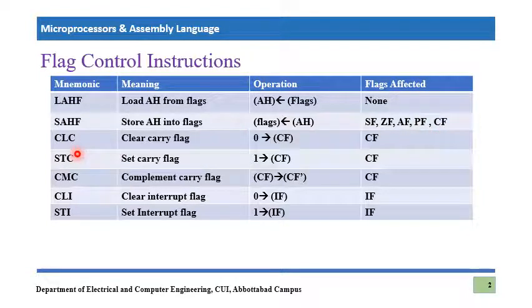The third instruction that we are going to see in this lecture is CLC. It is a very simple but very useful instruction, because there are a number of times when we need to clear the carry. If there is a carry and we don't want it to be present for the next execution, we can clear it in advance by just using this instruction, CLC. It's like clearing the screen in any high level language, CLS, the mnemonic of that command, clear screen. But here we are seeing clear carry. So if we want to clear the carry, we just need to use this command.